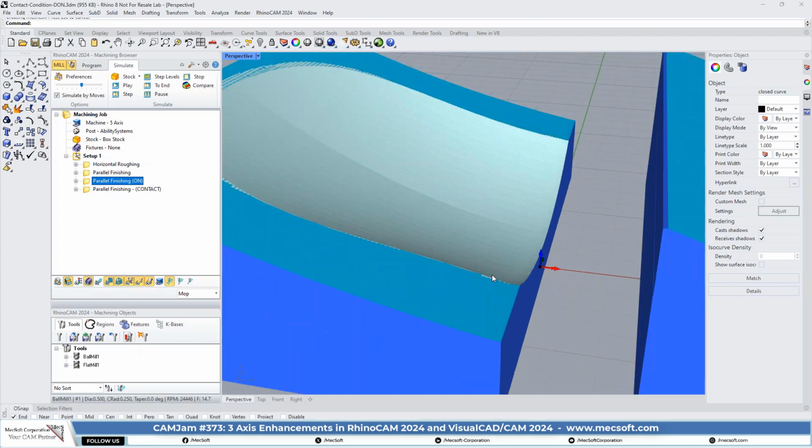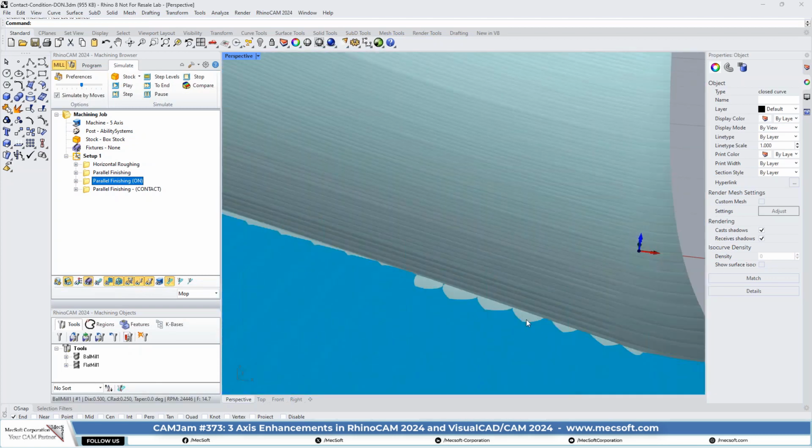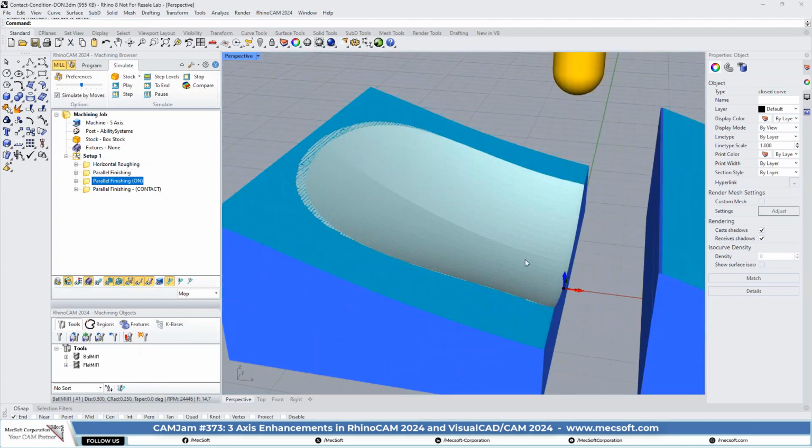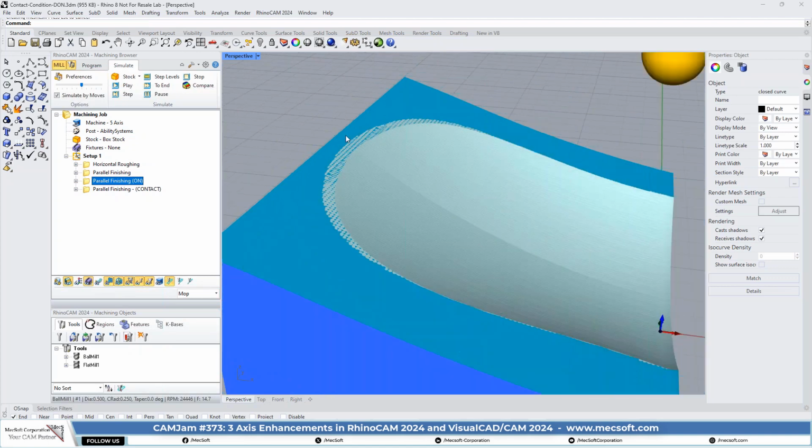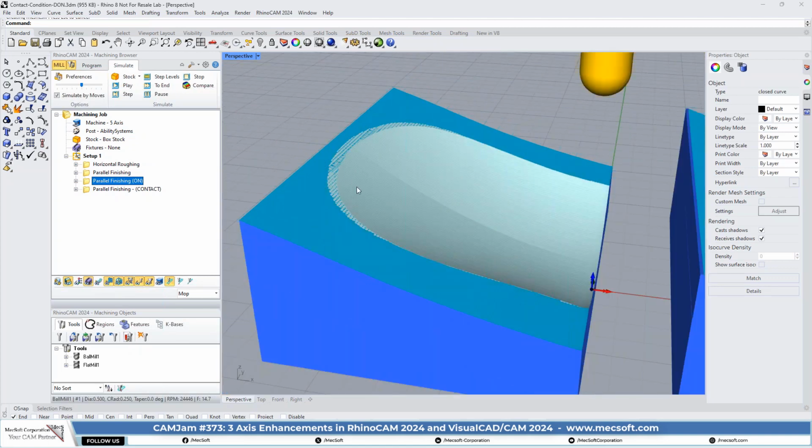So you can really get an idea of how the parting line is violated based on the tool, the axis of the tool aligning itself on the perimeter of the cavity. And as you can see, the tool rides up over the cavity, and this is all flash in the actual part. If you molded this part, you would see flash in these areas because that parting line was violated.